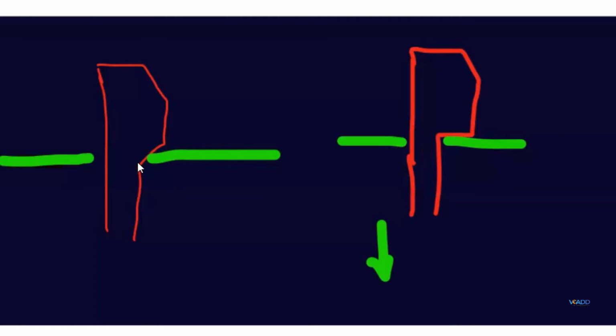No, right? Here we have a taper so that it can slide on the taper and be removed. But here it's a sharp, flat step, so it cannot be removed. So that is one example of considering the serviceability of the part.